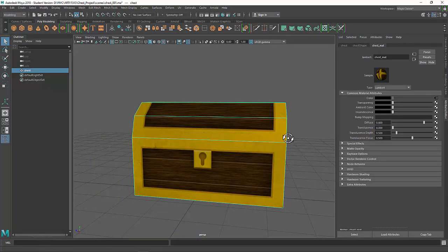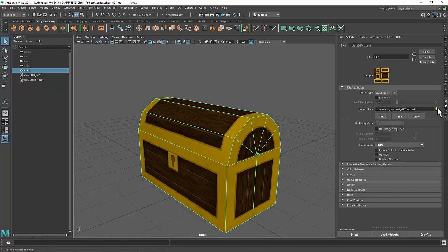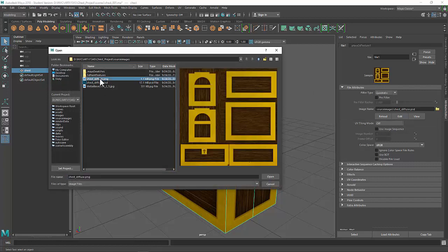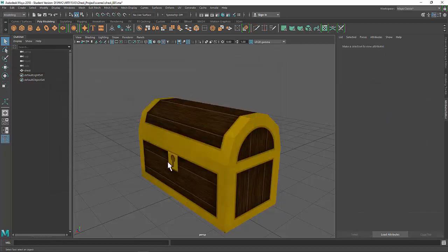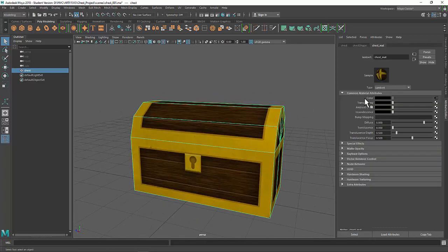And then in Maya, I can just plug in this new file. We'll go here. We'll browse to our new PNG, open that up, and take a look. Now, just as a random thing here, sometimes PNGs in our material, it'll hook up to the transparency channel. So if that happens to you, you can just right-click and say break connection. It would say that here. If I right-click on the color, we can see it, break connection. So if your PNG hooks up to the transparency channel and gives unintended results, then you can get rid of it.